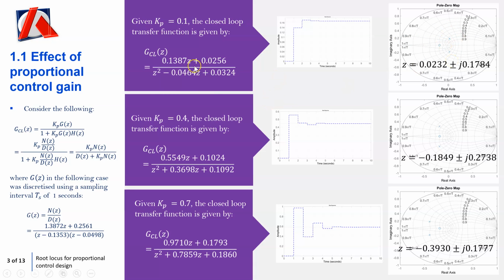This gives effectively the same result as using the open loop transfer function with the rules of root locus. You would notice exactly the same effect: a circle where one open loop pole broke away and went to the 0, and another broke away and went off to minus infinity.